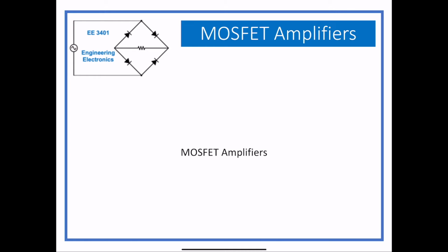So when we look at the AC circuit, we will know everything about the DC circuit, but the DC circuit will be turned off for the analysis part. So anything that's connected to the DC circuit looks like ground to AC, because that's how we're doing the analysis. And it will make more sense as we go through and do it.